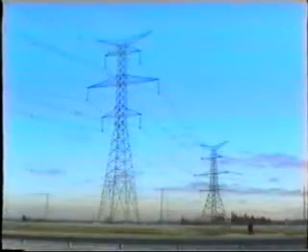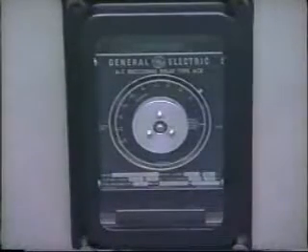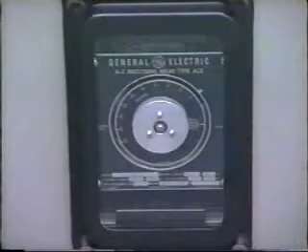On high voltage transmission and sub-transmission lines, we usually want the line to reclose as quickly as possible so as to help maintain stability. This is usually carried out by the instantaneous setting on the reclosing relay. However, a small time delay of about half a second, that is 30 cycles, must be allowed before reclosure so as to permit the arc to extinguish at the fault.